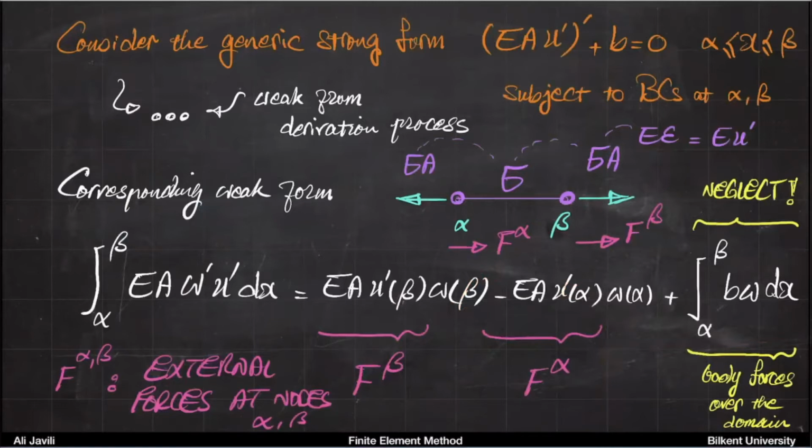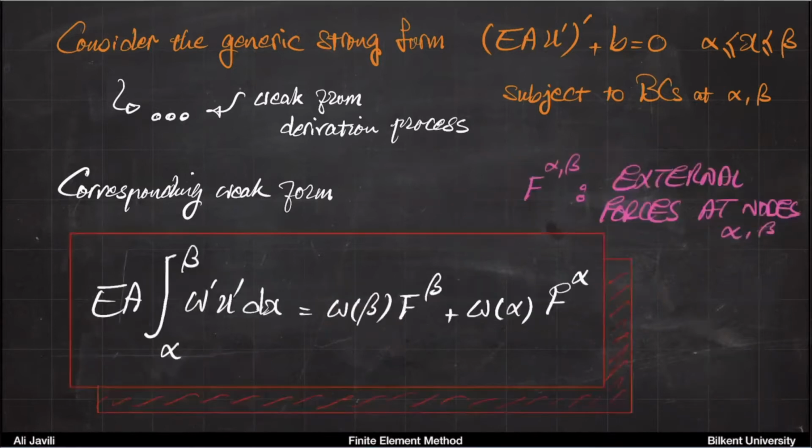Now, to give you a feeling of what that weak form means, we also started interpreting the meaning of the differential equation in its weak form sense. And we realized that these terms on the right-hand side are basically the forces. They are the forces at nodes. And then we also discussed this many times, that if you have a truss structure, you apply the forces at nodes. So there is nothing limiting in that sense about this.